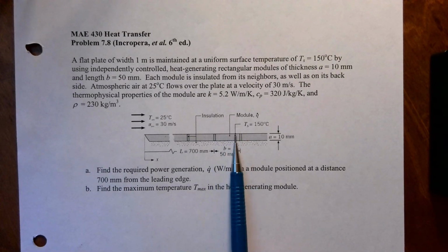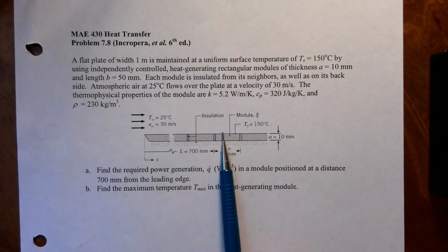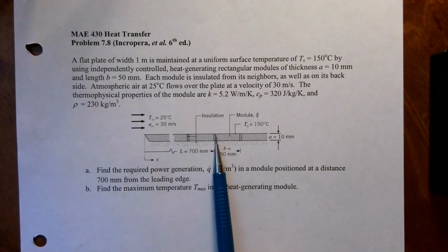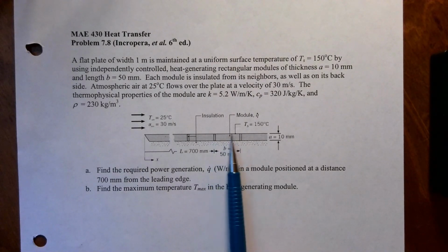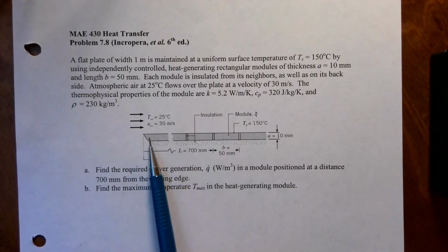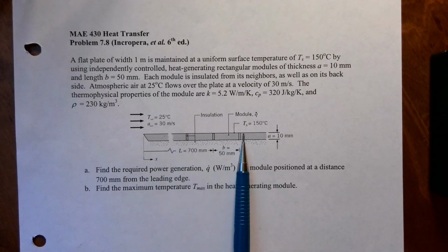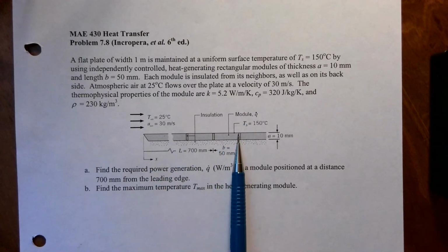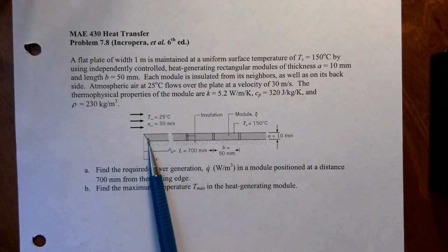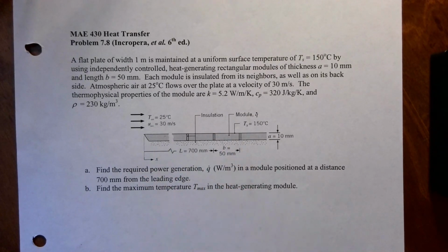So there's a lot we have to figure out. Are we in the laminar region, the turbulent region? Are we maybe partially in laminar or turbulent? And when we calculate the average, we only need it over this small domain from there to there, not from the front edge of the plate. So there's some thinking that's going to be involved here to use the correlations that do start from the leading edge of the plate.